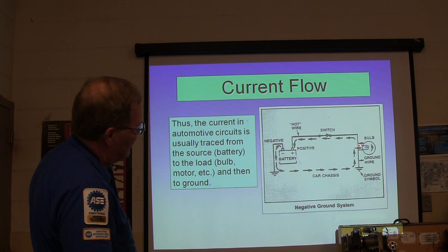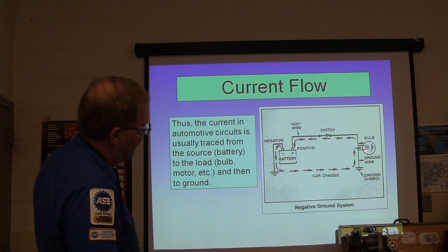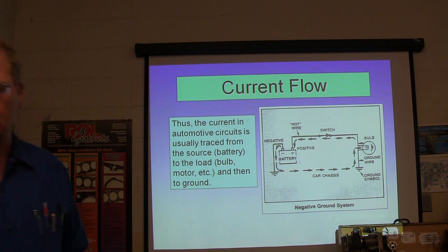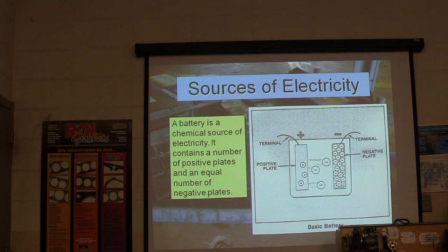If I just measure it right here and I don't find any power, if my test light don't light up there, I still got to go find out where it is. If it's a bad switch, or if it's a bad connection here, bad ground, whatever. You know, that's where we're headed. This is the way we start out.